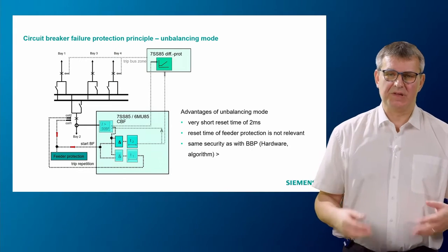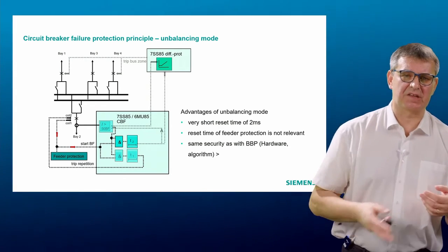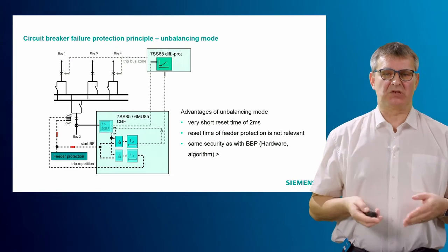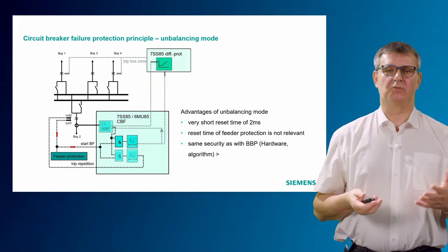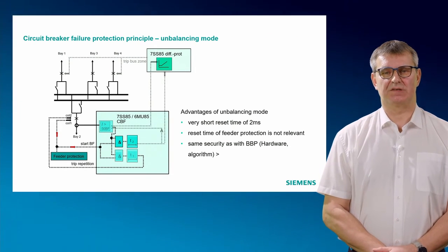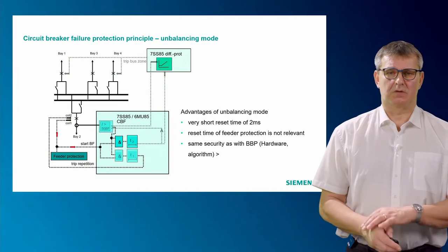And okay, the reset time of the feeder protection, the reset time of the transformer protection device or anything doesn't matter. So we have really the same security as with the busbar protection device.